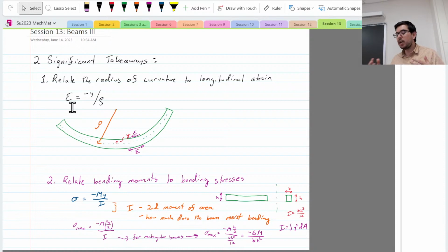And there are also techniques that we use, like making I-beams, so that you have a high I, meaning high second moment of area, but with a reduced amount of mass. That's why you see a lot of hollow beams or a lot of I-beams, because you don't need all that mass to get all the resistance to bending that you are interested in having.